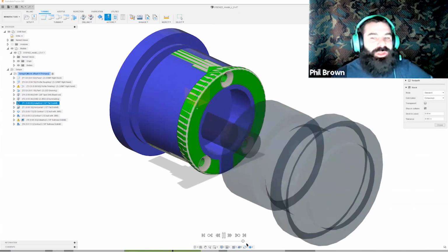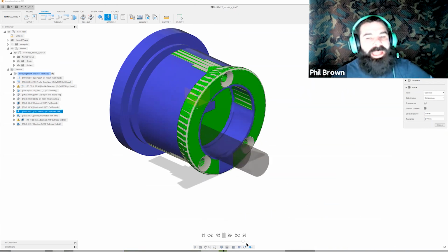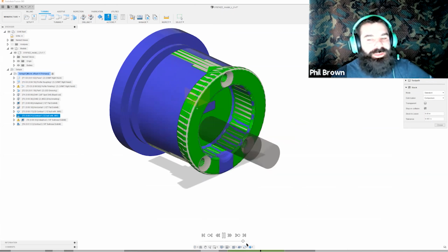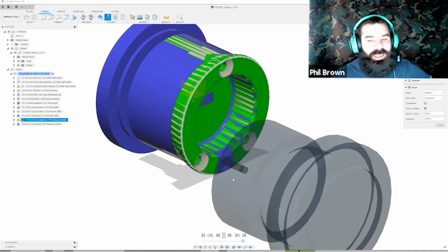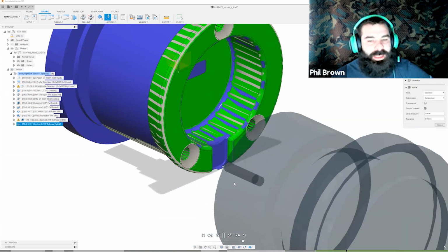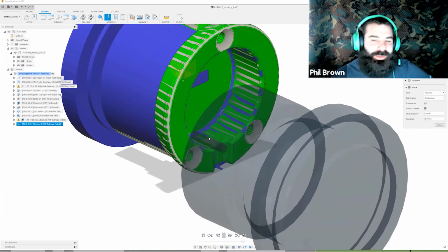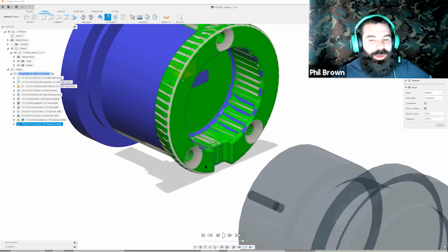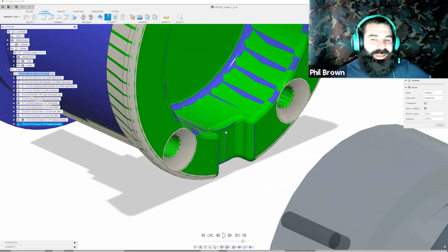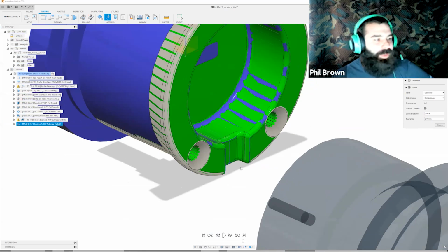On the idea that it could be a mill or a lathe again, I can bring all that information into Fusion 360 and use that to my advantage. So now you can see my smaller tool path coming in. I'm now cleaning up my walls and my floors, and that little nastiness all the way down there, I may need to trim out. We are going a little further than expected. And then there is a little flat here that I may want to clean up in between those two.